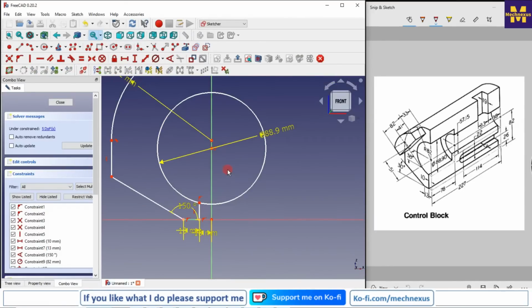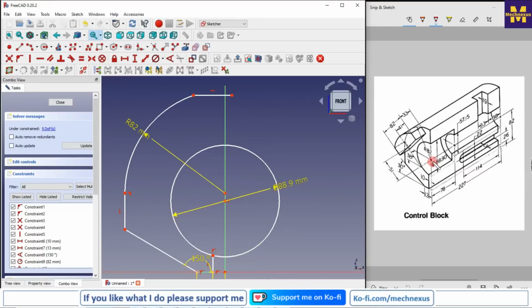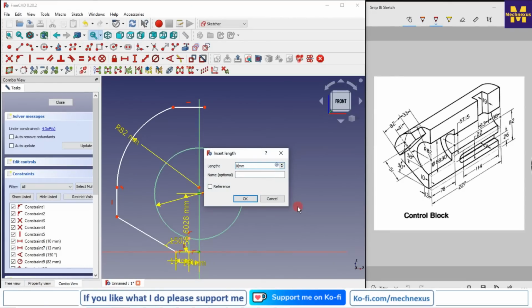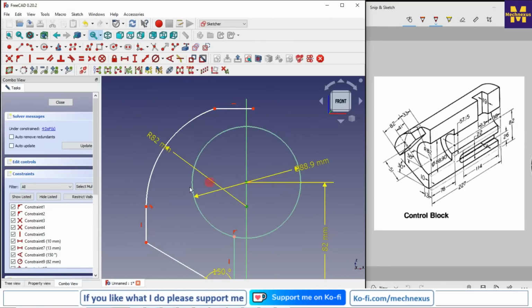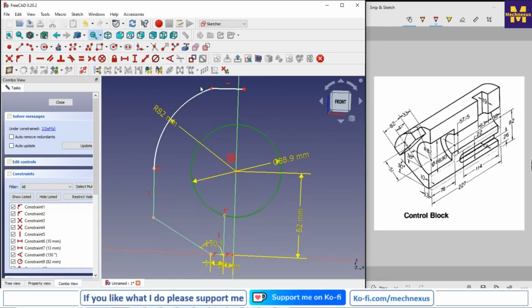and we will find the center from the edge. So it is 82, which we can see here. So I will give it dimension 82, and I will merge this center. And now I will make it construction,